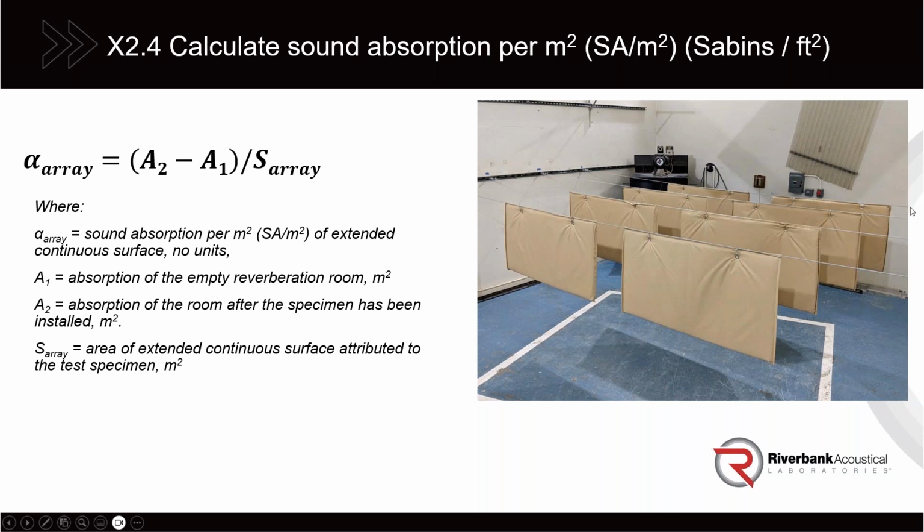All right. Do you foresee any type of standardization in mounting methods for baffles for testing purposes, similar to what we have for suspended tiles and panels? Yes, in fact, thank you for asking that question. There actually is. ASTM E795, that same document that standardizes mounting types for wall panels and ceiling tiles, also has a standard mounting for acoustical baffles.